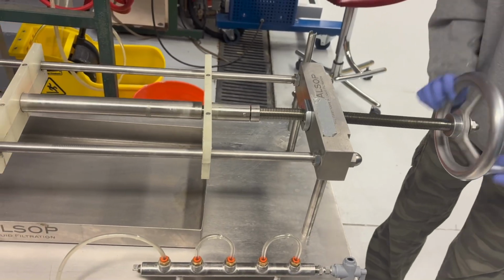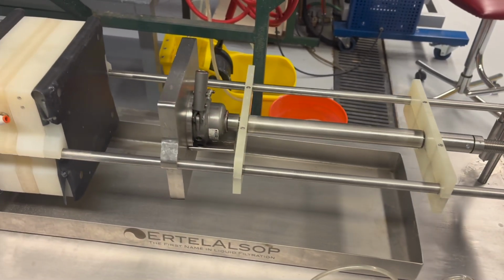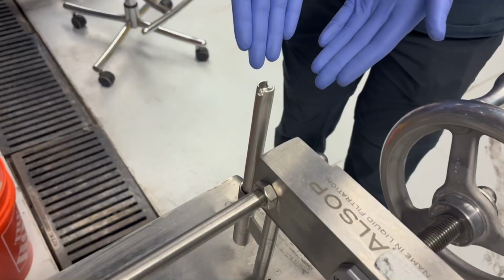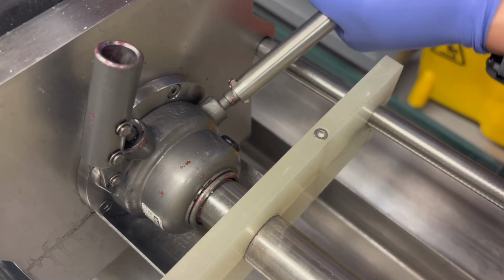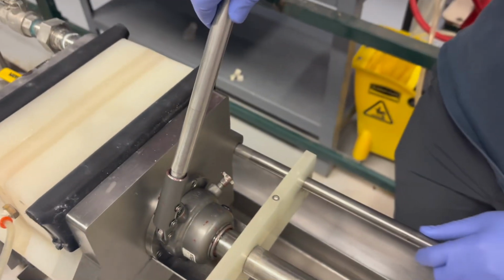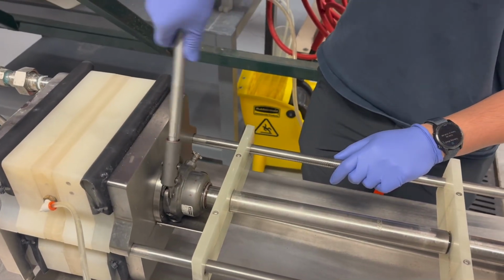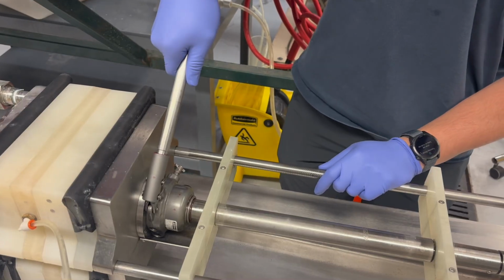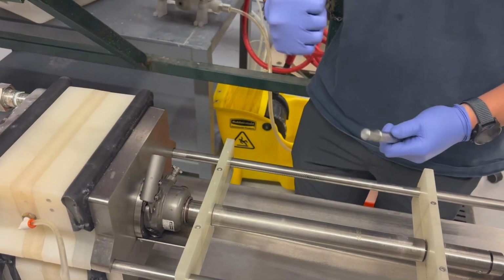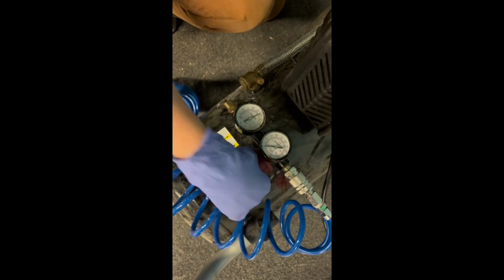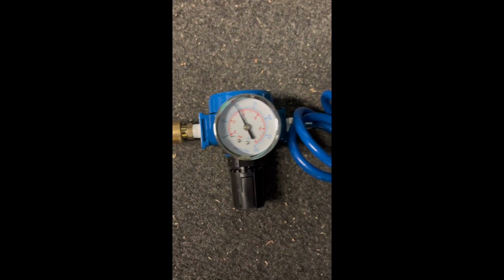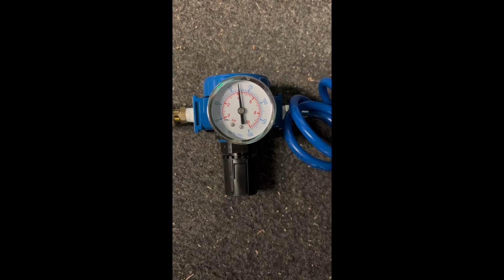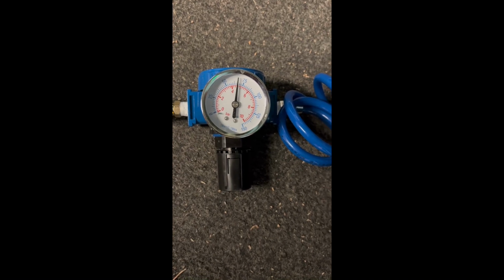Before operating, ensure all 3 plates are aligned and hand tighten the press closed. Once hand tightened, use the jack to seal the filter press shut. Once this step is complete, the trial is ready to begin. After turning on the air compressor, make sure the regulator is set to 60 psi, never exceeding 100 psi, as that is the maximum operating pressure of the diaphragm pump.